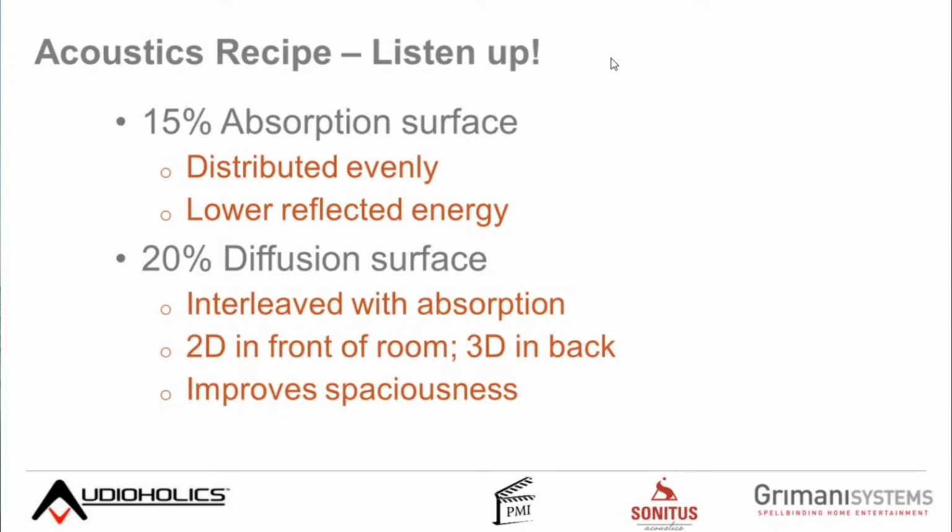And the result of having scattering panels in the room is you improve the sense of spaciousness, and you actually fool your ear brain to feel that you're in a bigger room than you really are. Because in big rooms, there's naturally some delayed reflections that are all kind of scattered out over time. And your brain education tells you, hey, I'm in a room with a bunch of scattered, non-correlated sound. It must be big. So you can actually make it.